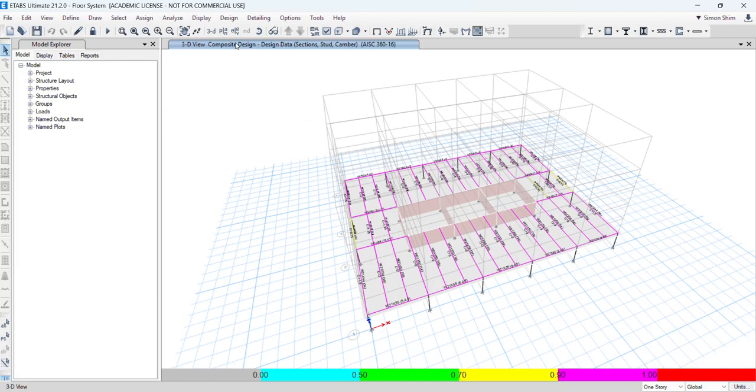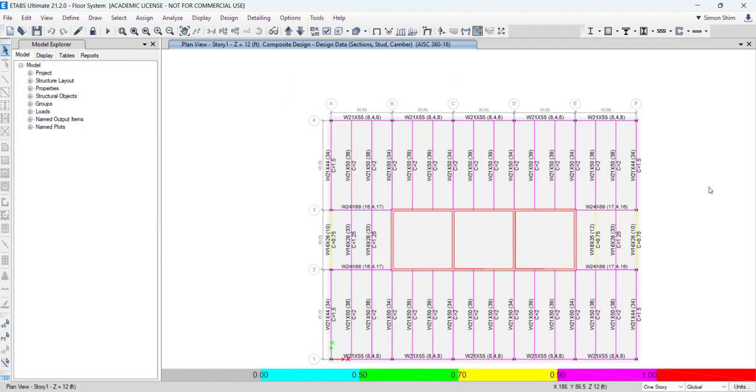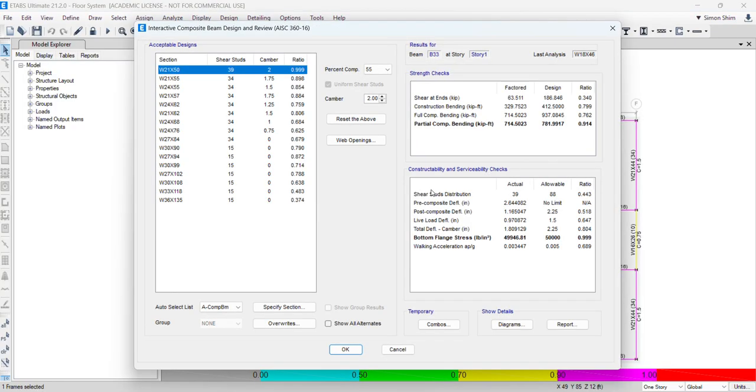All right, so let's put this one on the plan view. First, run ETABS and show some recommended beam sizes. Since it's 45 feet long, right click, and we'll choose one typical beam. You see, in the auto selection groups, they showed all the beams are workable, right?